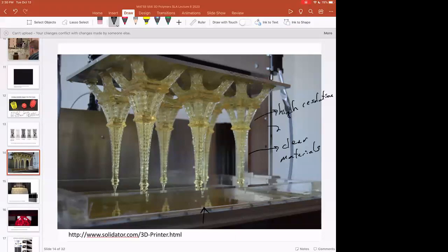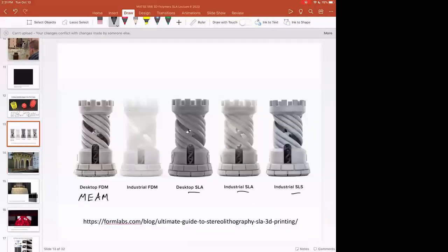Really between 25 to 100 microns. And if you remember, in SLS and material extrusion AM, the surface roughness of the parts and the resolution of the parts is on the order of 50 to 300 microns. And so you can easily see the surface finish and some of the resolution differences just by looking at the part. Then, of course, you can use optical profilometry or stylus profilometry or something else in order to get fine measurements of surface roughness.